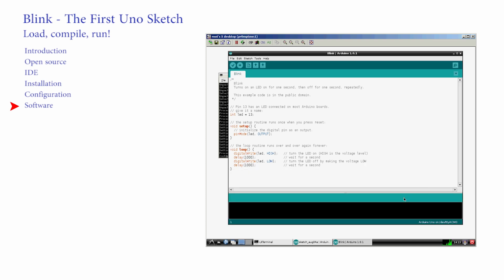For the moment, we need to know how to check that it is correct and how to load and run it on the Arduino. There are two circular buttons at the top of the package. Click the first tick box to verify that the code is correct. It should be. Clicking on the second right arrow button also checks the code before compiling it. Compiling is the process of taking the code and turning it into ones and zeros that the Uno understands.